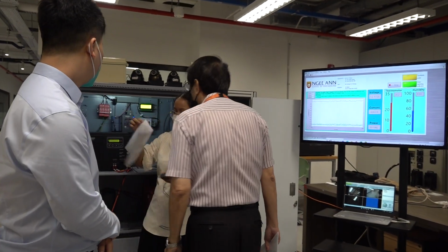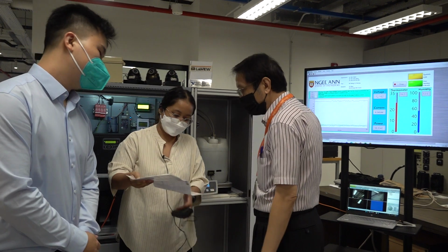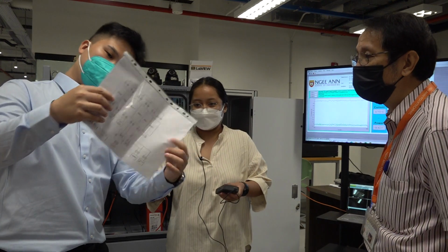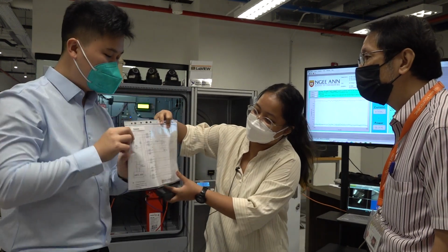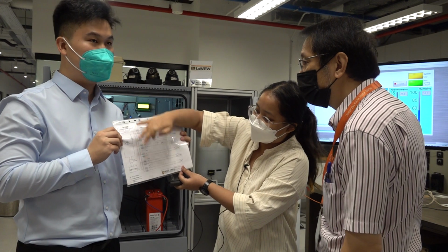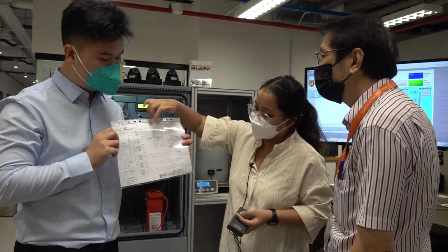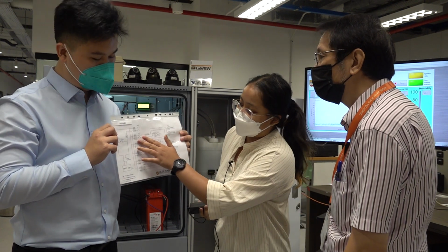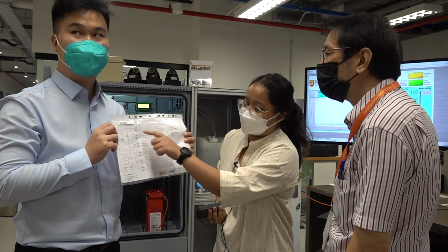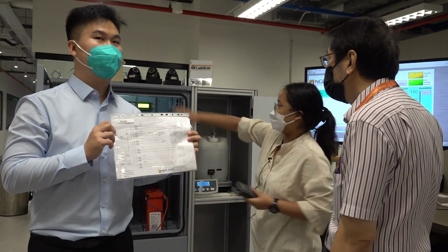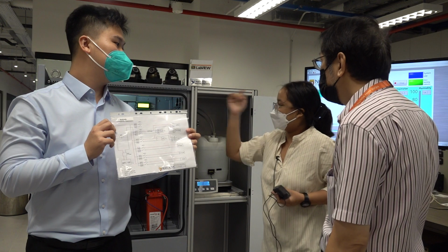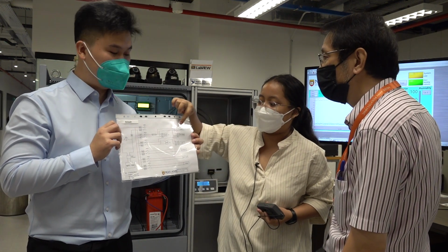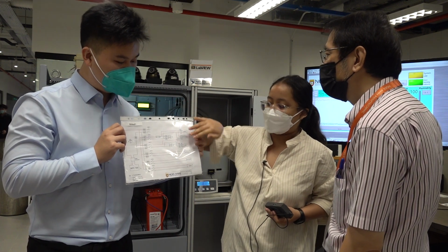Okay, so what I did is a schematic and a single line diagram. So you only look at the single line diagram. This is the MFC and the battery. We label the MCBs 1, 2, 3. We use up to 6 MCBs. Usually the battery is the most important thing, so we put it all the way to the right-hand side of the cabinet. On top of that, the second most important thing is the myRIO. After the myRIO will be all the sensors.